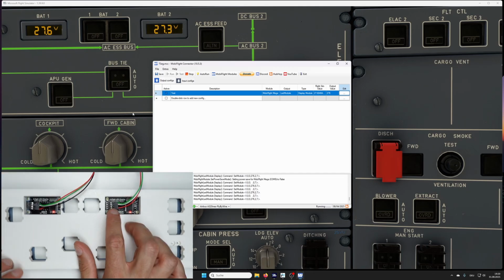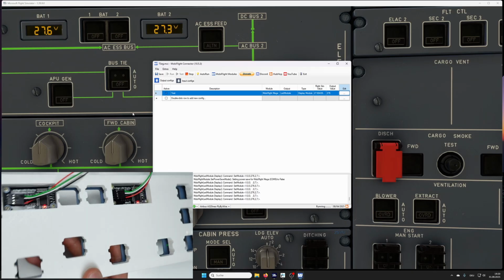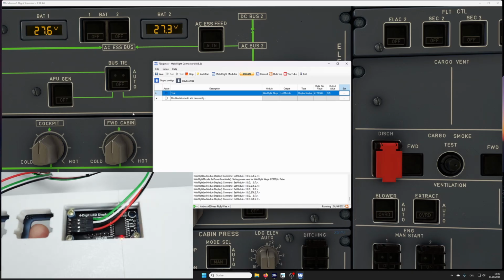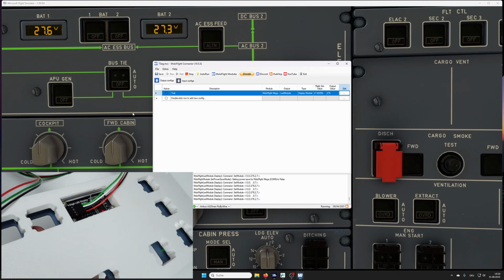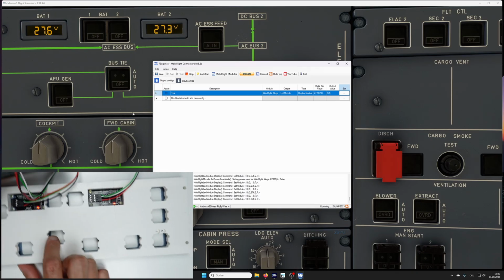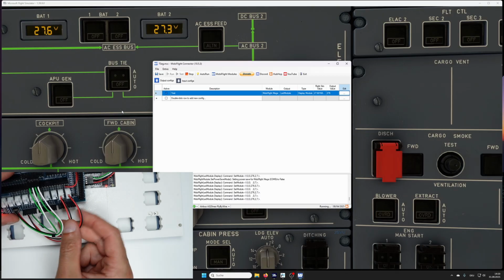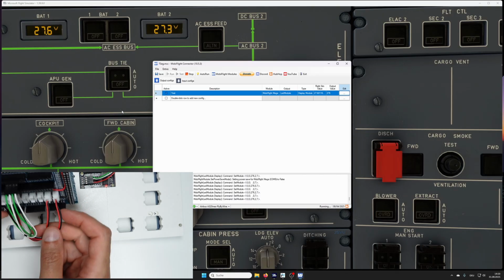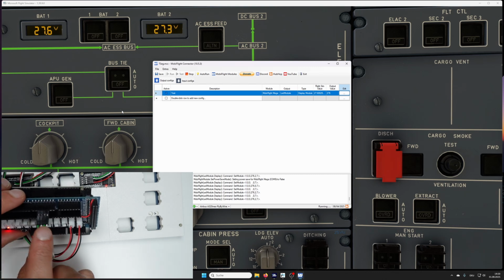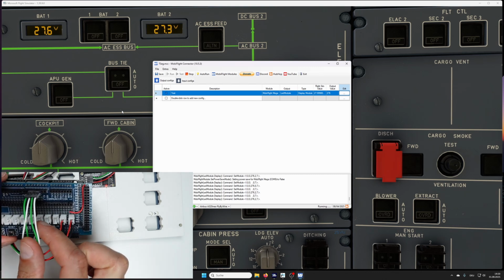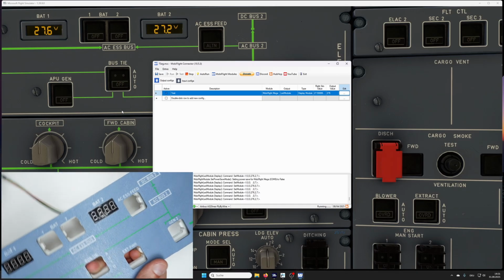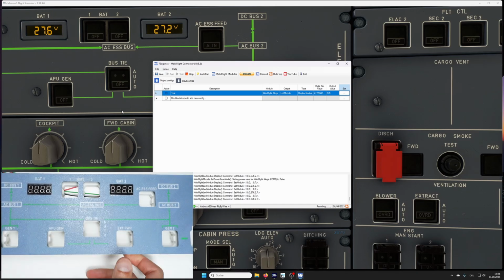These 2 displays are just mounted with some wooden screws and some spacers in the panel, and then connected with 2 connectors to the Arduino power supply, and then 2 DuPont connectors on pin number 2 and 3 and 4 and 5 for the right display.